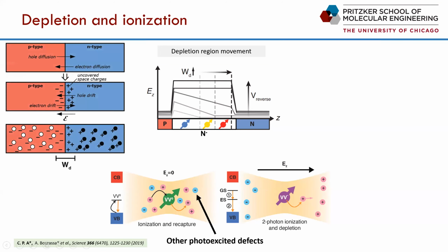And that's the same reason then for this creep in the intrinsic depletion region there? This growth of the electric field profile is just related to the fact that our device isn't purely intrinsic. There's actually a small amount of residual n-type impurities in this layer. And so just like in a regular PN diode, we first form our depletion region at this PN interface, but only after applying enough reverse bias that we fully deplete that layer do we make it to the more highly doped layer deeper down.